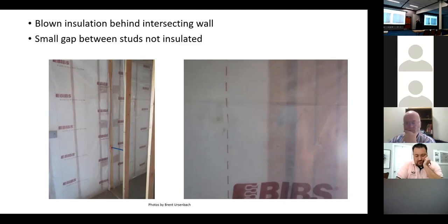So they came perpendicular off the outside walls, 17 walls, 10 foot high. And the framer, when he framed, he put a vertical stud on both sides for backing in the outside wall, so that when you did your corners, you had backing all the way around.